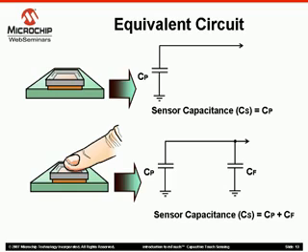We should mention here that the capacitance introduced by the finger is known to be very small, in the area of 5 to 15 picofarad. Therefore, we will want to ensure that the capacitance created by our pad is small as well to make certain that a touch is sensed. Further information on physical design guidelines can be found in application note number AN1102, referenced at the end of this web seminar.